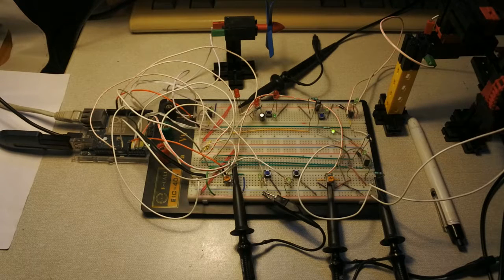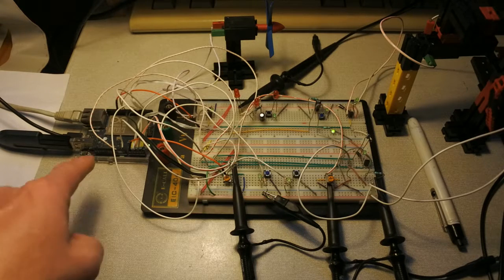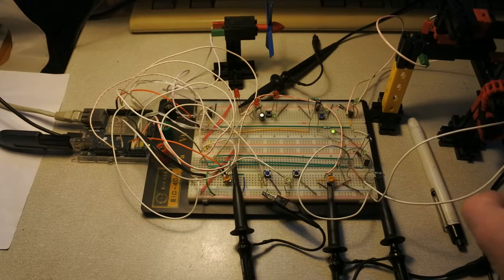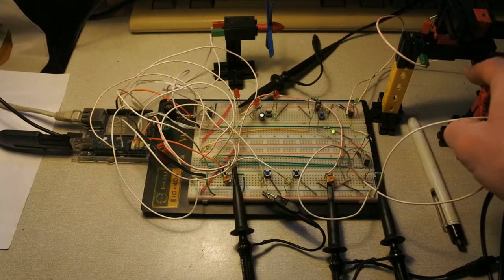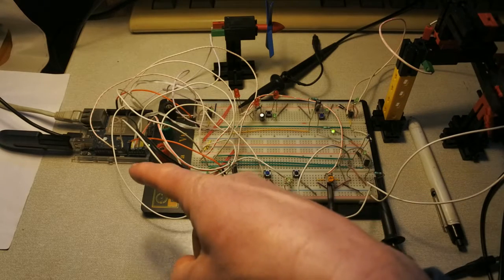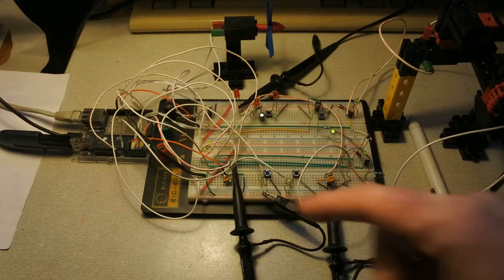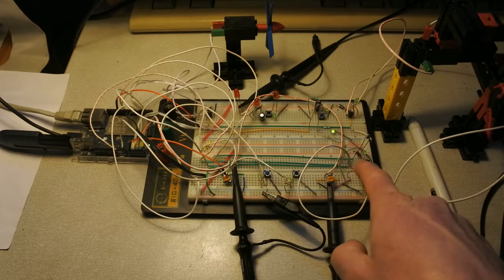And the voltage divider I am using to protect the input from high voltage, because this one works with 9 volts, and I'm talking about the phototransistor that you can see here. With 9 volts I would blow up at least the port that I'm using, hence the voltage divider.